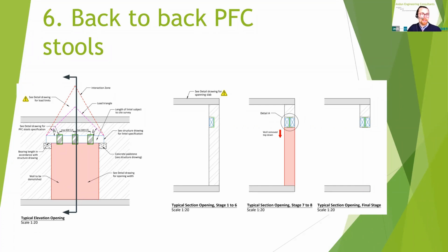And that's that design in a nutshell. It's very helpful and removes the requirement for any propping, because the load path remains within the wall until the lintels take the load, and then that's the permanent works loading. So that's the loading it's going to have in the permanent case.